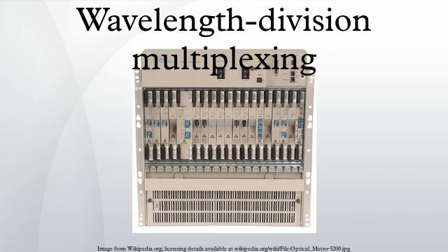This is a remote amplification site that amplifies the multi-wavelength signal that may have traversed up to 140 km or more before reaching the remote site. Optical diagnostics and telemetry are often extracted or inserted at such a site, to allow for localization of any fiber breaks or signal impairments. In more sophisticated systems, several signals out of the multi-wavelength optical signal may be removed and dropped locally. A DWDM terminal demultiplexer.